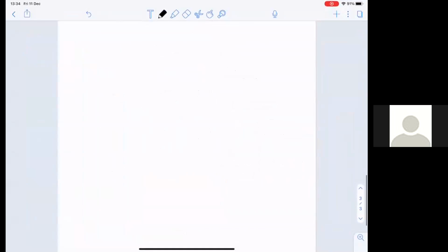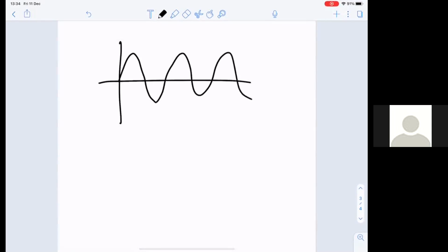So you might be asked to draw the AC/DC currents, and it is pretty straightforward to draw. Make sure you get the axes and the units right. So this will be your AC graph, right? Put volts, but you could easily have current on the y-axis, and obviously put time on the x-axis. You want to make it a sufficiently long scale of time, so you have milliseconds.